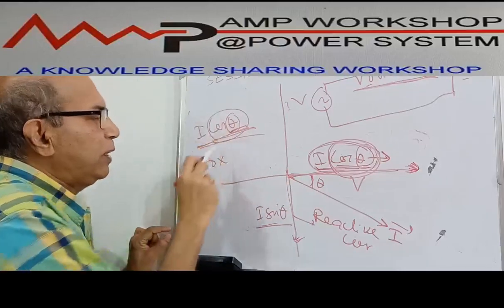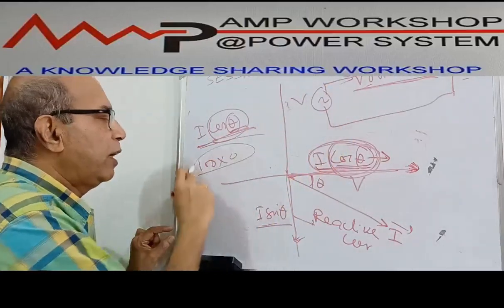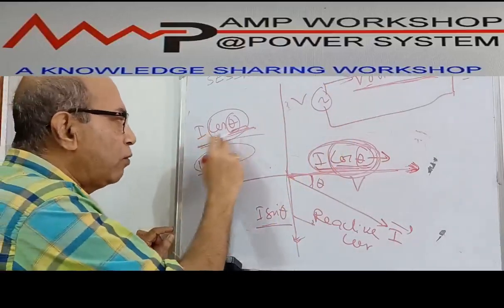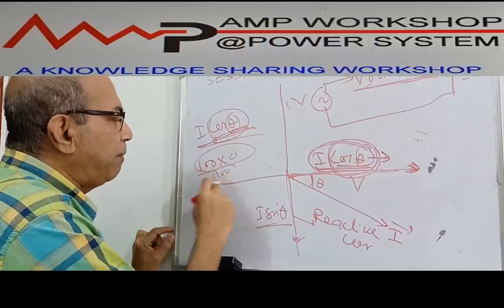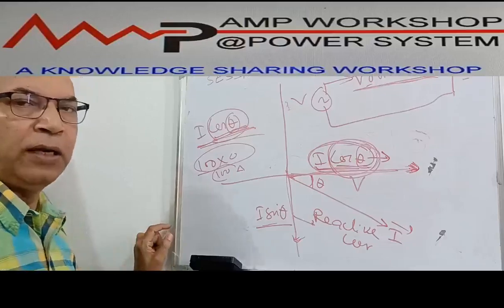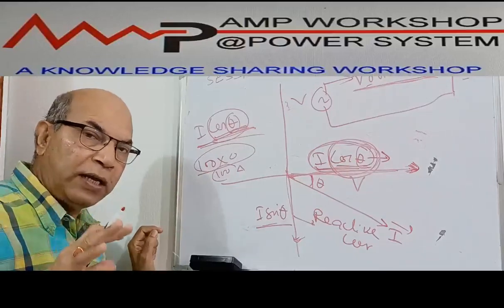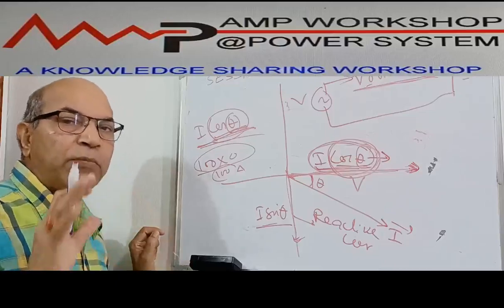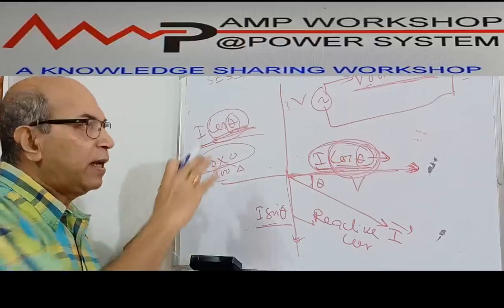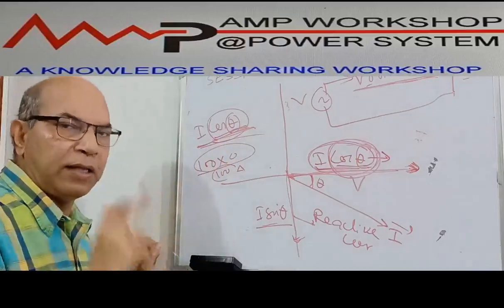If cos theta is 0, the circuit carries 100 ampere but gives no power. If cos theta equals 1, it gives full power from the 100 ampere. This value has a great impact on the current magnitude which can give power, and indirectly it can reduce the carbon footprint and help control environmental conditions, so it has a huge indirect impact in the end.